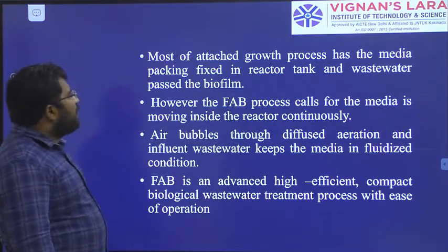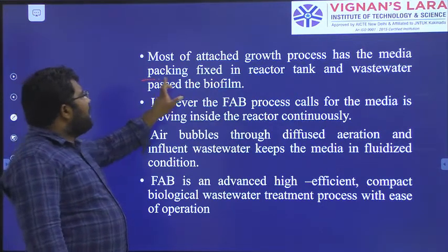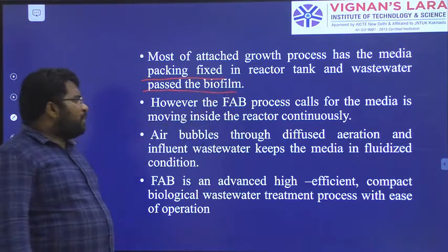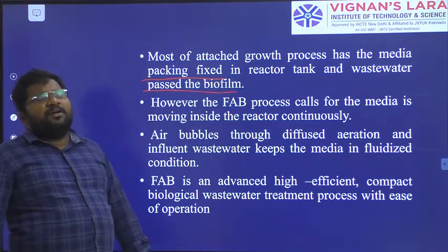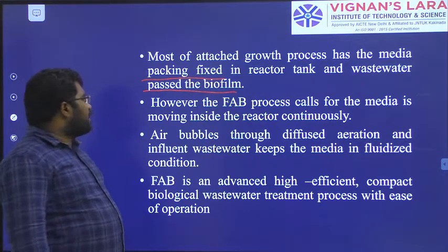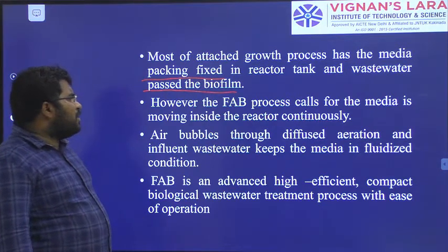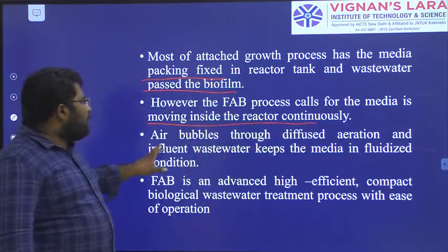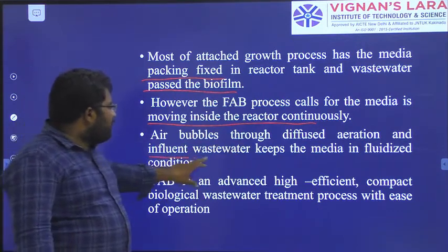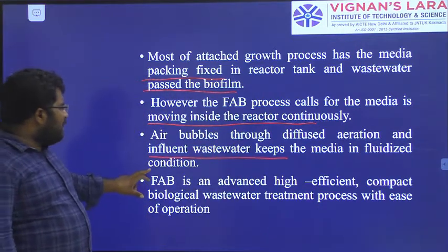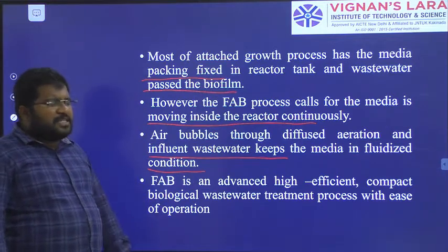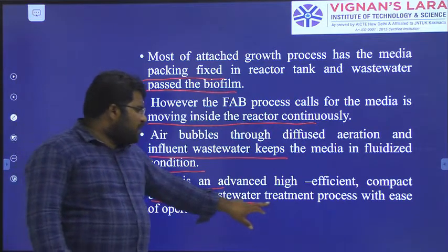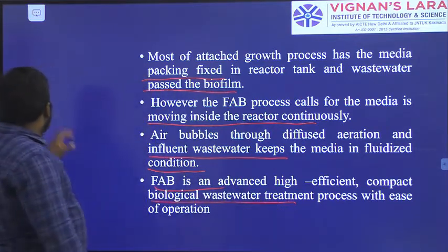Okay, so most attached growth processes have the media packing fixed in the reactor tank and wastewater passes over the biofilm. Okay, so normally we already saw this in the case of the fluidized bed reactor. However, the FAB process calls for the media to move inside the reactor continuously. Then air bubbles through diffused aeration and influent wastewater keep the media in a fluid condition. It is similar to a fluidized bed. Okay, so FAB is an advanced, highly efficient, compact biological wastewater treatment process with ease of operation.